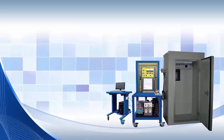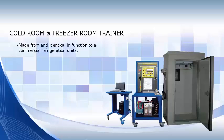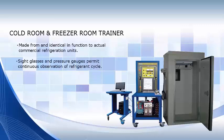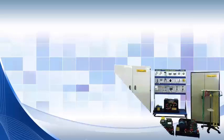This picture shows Labtech's cold and freezer room trainer. This walk-in trainer is made from actual commercial refrigeration units which have been modified to meet the needs of training labs and workshops. This trainer is ideal for exploring the operational and functional characteristics of condensers, evaporators, compressors, and control devices. Strategically placed sight glasses and high-low pressure gauges permit continuous observation of the refrigerant cycle, as well as observation of the refrigerant after condensation and prior to expansion. Hand valves allow the refrigerant to be restricted and thus simulate system malfunctions for troubleshooting.